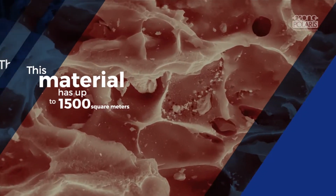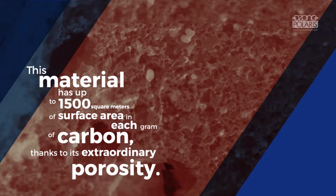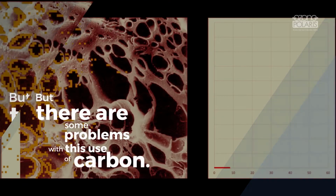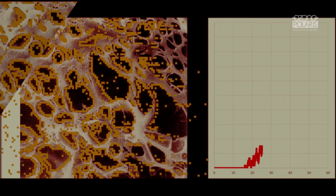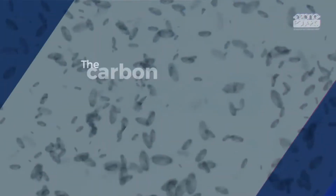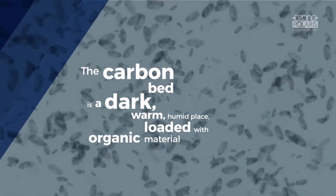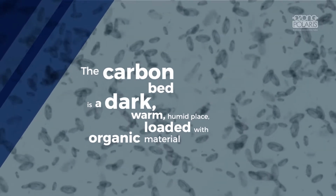This material has up to 1,500 square meters of surface area in each gram of carbon, thanks to its extraordinary porosity. But there are some problems with this use of carbon. As contaminants in the water adhere to this surface area in the pores of the carbon, its absorption capacity becomes exhausted, and the contaminants begin leaking through the filter. The carbon bed is a dark, warm, humid place loaded with organic material. Ideal conditions for bacterial growth, which can escape with the effluent water.